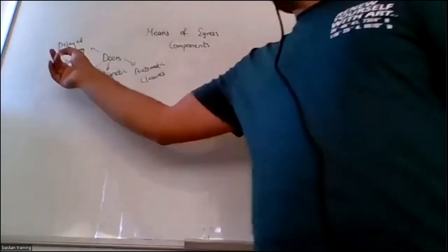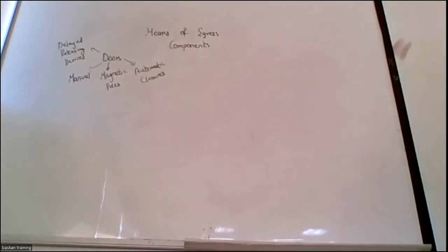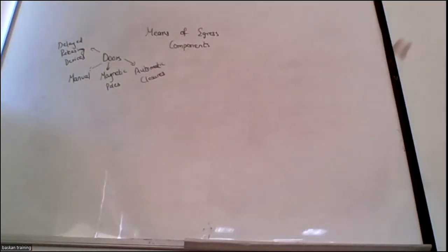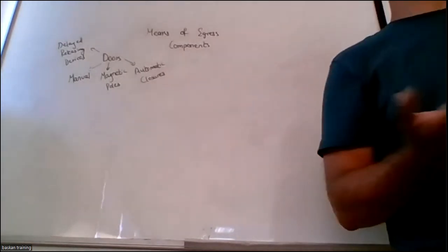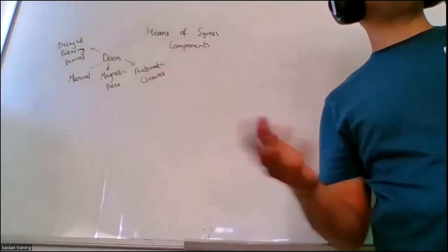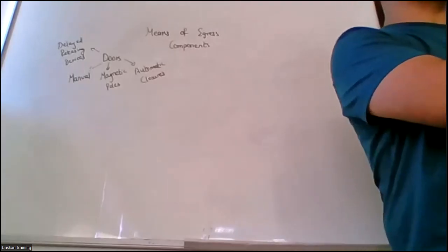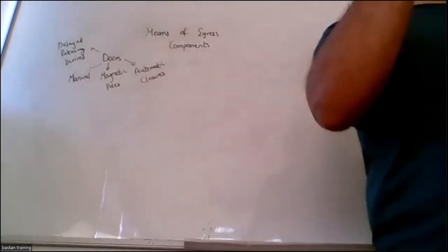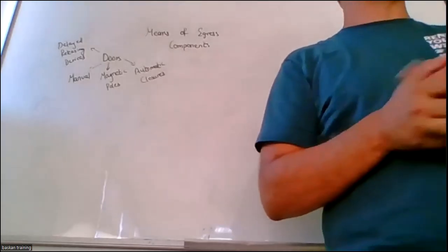Doors with delayed releasing devices, DRDs, are usually available for those areas where we don't want unauthorized personnel to enter. It could be in healthcare occupancies, let's say, in hospitals. In a panic situation, we don't want people to enter the ICU rooms. When they are panicking, they will find any open pathway and rush there, but you don't want them to enter the critical patients area. So they are always protected by delayed releasing devices. In other words, a specific access control is required to open those doors.